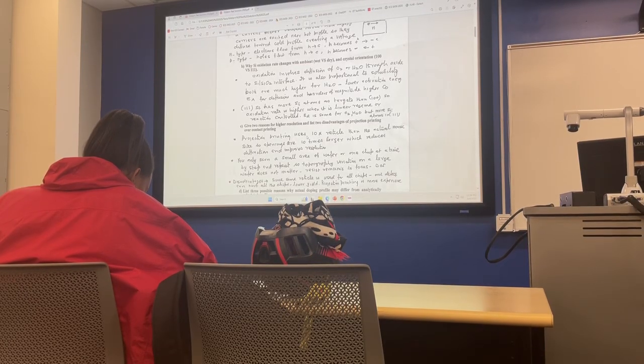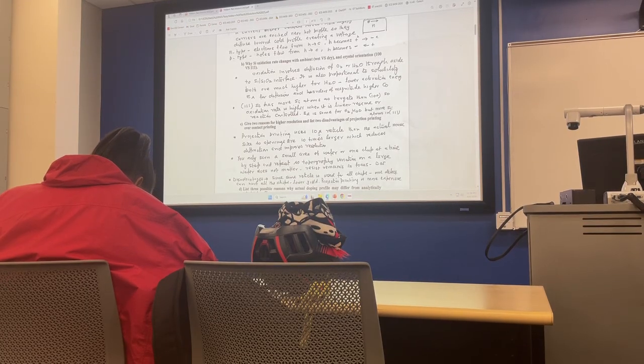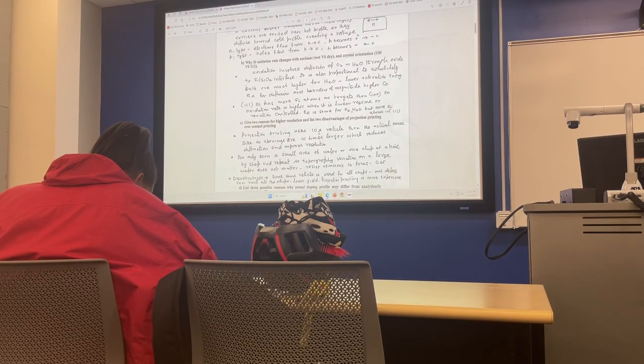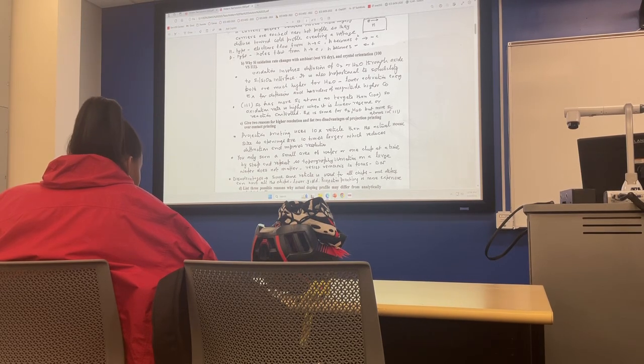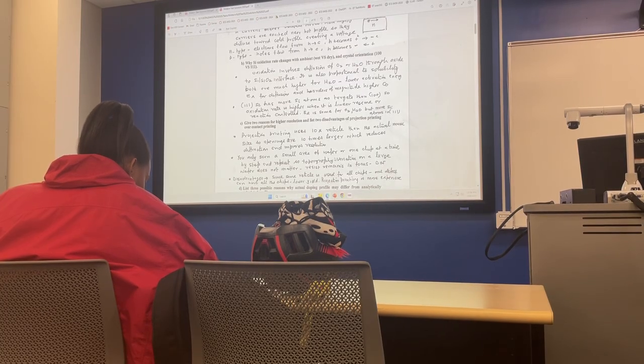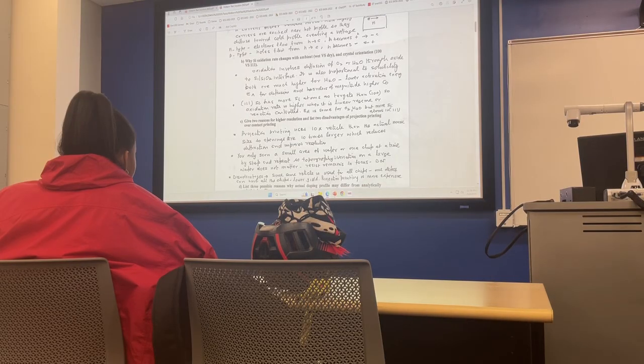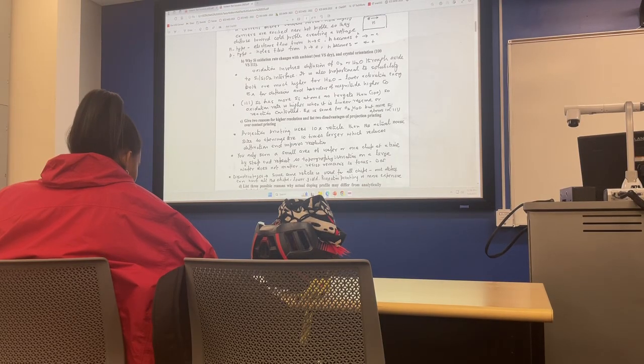And the second, the most important one, is that you have the luxury of making the gaps or holes much larger, so light can go straight through without getting diffracted. The two disadvantages that most of you got all right: one is that it's very expensive and very slow because you are exposing one chip at a time on a wafer, not the entire wafer. So it has a lower throughput and it is more expensive, right?